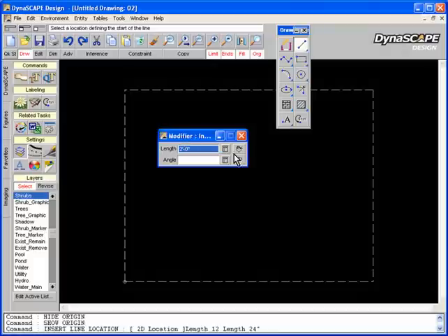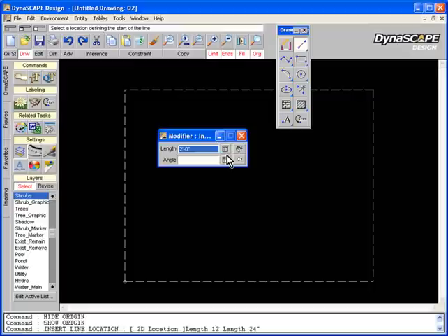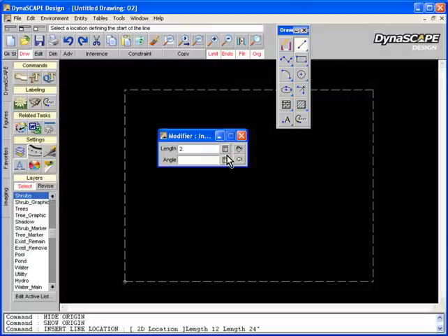If you want to insert feet and inches, you can do it two different ways. You can do feet and then use a decimal and 5. 5 will convert that to inches, will be half a foot, so it'll be 2'6". Or you can type in 2, use the foot symbol, and add the value 6. You don't need to insert the inch symbol because once you've inserted the foot symbol, it knows the next value is going to be inches. All you need to do is hit spacebar or enter, and it will add the inch symbol to that.